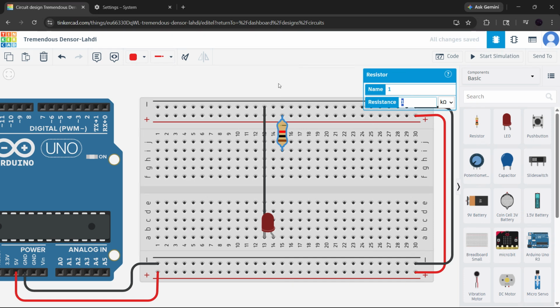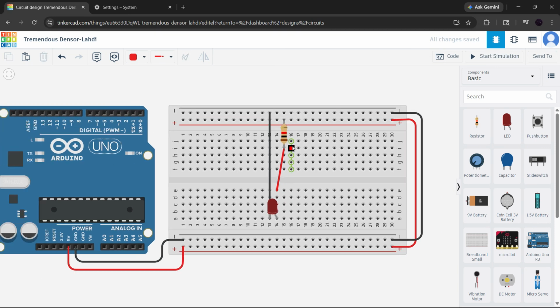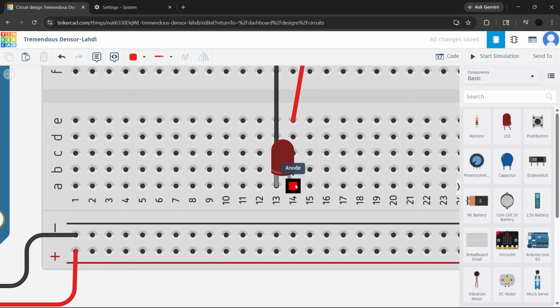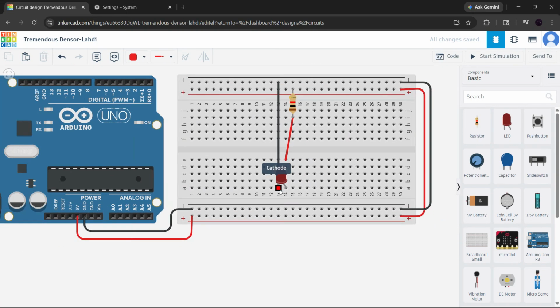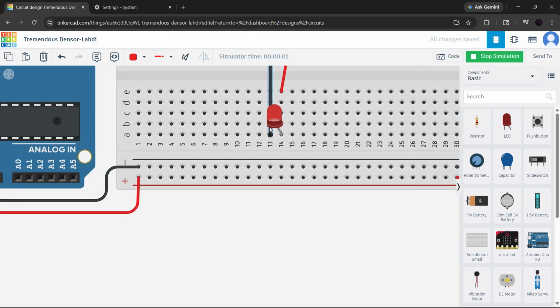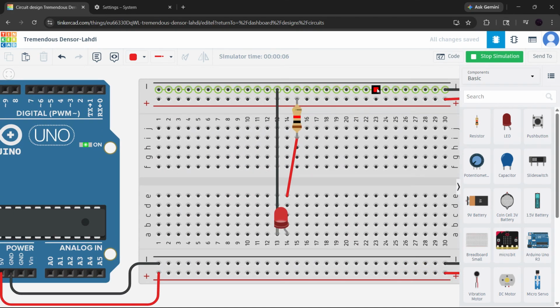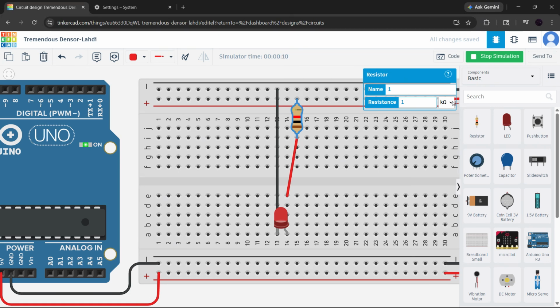If you're using an LED, check the polarity carefully. The anode, which is usually the bent or longer leg, depending on the component view, should go to the positive side. The cathode should go to the negative side. And for most standard LED circuits in Tinkercad, you should use a 220 ohm resistor to protect the LED and keep the simulation stable. If you skip the resistor or use the wrong one, Tinkercad can sometimes act like the virtual bulb is broken or overloaded.